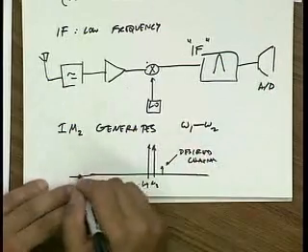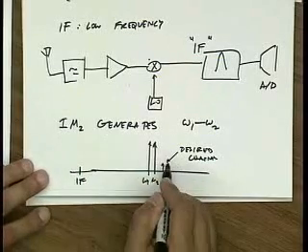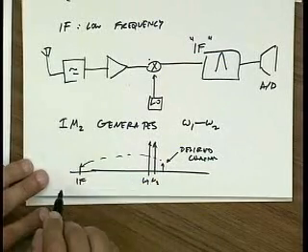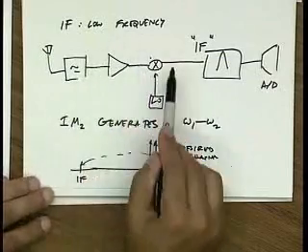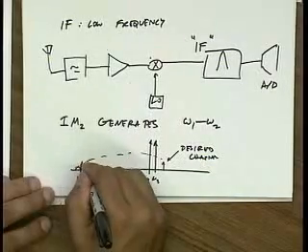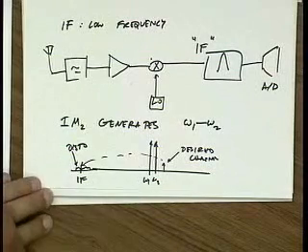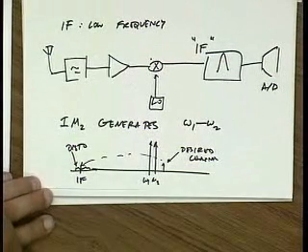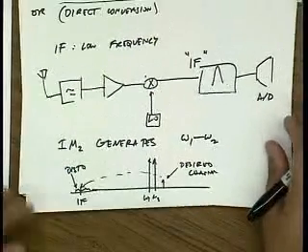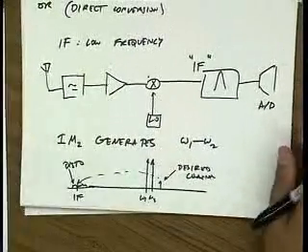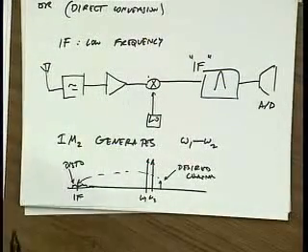And let's say that this is my IF. So my system tries to convert the desired channel to the IF, but because my system has some second order distortion, maybe in this LNA, maybe in this mixer, it will generate distortion that will compete with my signal and possibly make it impossible to communicate. All right? So even narrowband systems are not immune to second order distortion. Any questions about that?